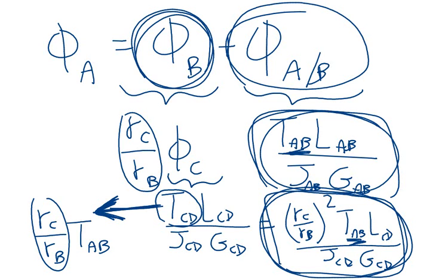Meaning you've already designed this system that you're trying to sell, and you need to come up with a value of torque. You want to tell your customer who you're selling this to: do not exceed this amount of torque on the free end. Don't hook up a motor that has a torque rating greater than this amount. Okay, so that's a design problem.